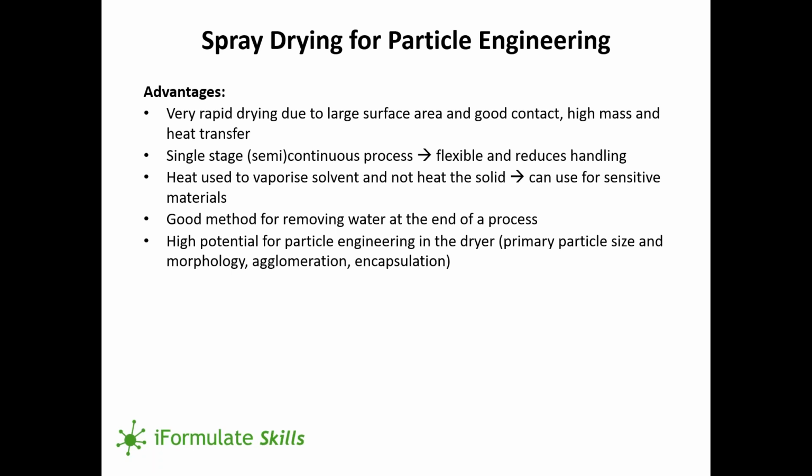If you get your conditions right, the heat can be used to vaporize the solvent and not heat the solid very much, so it's got potential for use for sensitive materials. And it's a very good method simply of drying. It's a very efficient way of removing water at the end of a formulation or a synthesis process, which might have given you a formulation with too much water in, and you want to get a dry product out of it. So it's simply as a method of drying, it's useful.